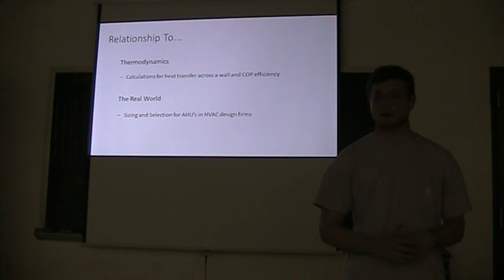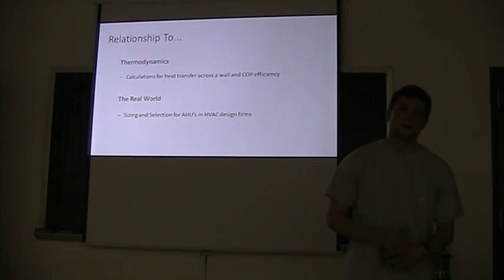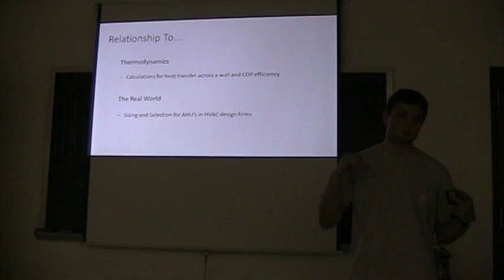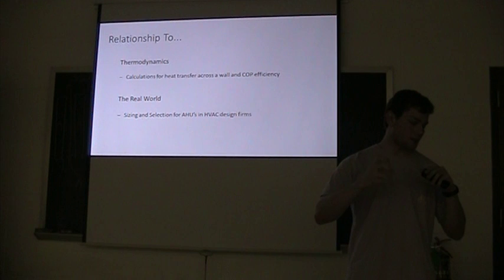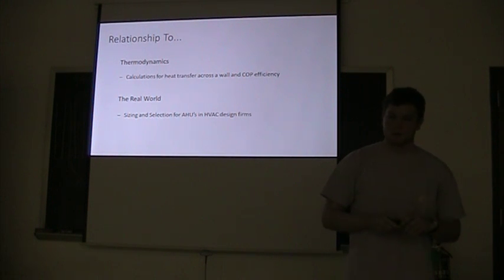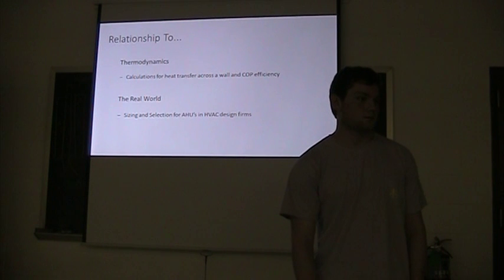I actually worked at an HVAC firm last summer and did a few jobs, and I remember that in some designs you actually don't need VAV boxes. Some designs you can just have your air handling unit go straight to the supply room, and then through the supply vents you can control with the little fins, little dampers, how much air goes in each room without actually having a mechanical motorized damper. So that's about it. Any questions?